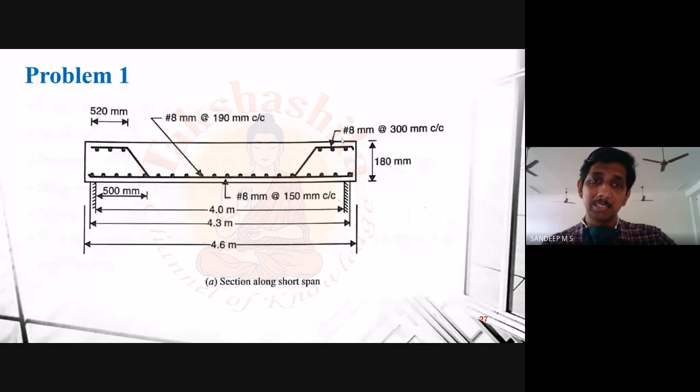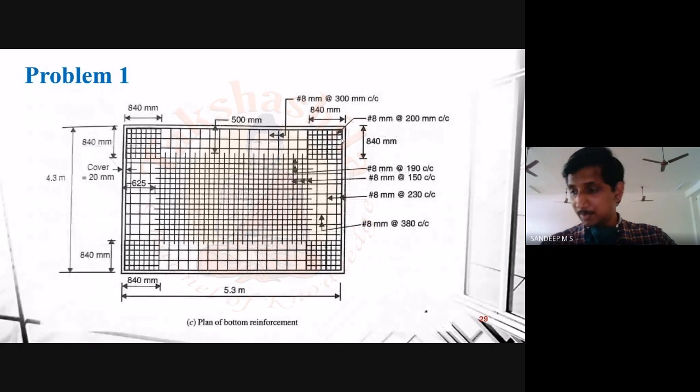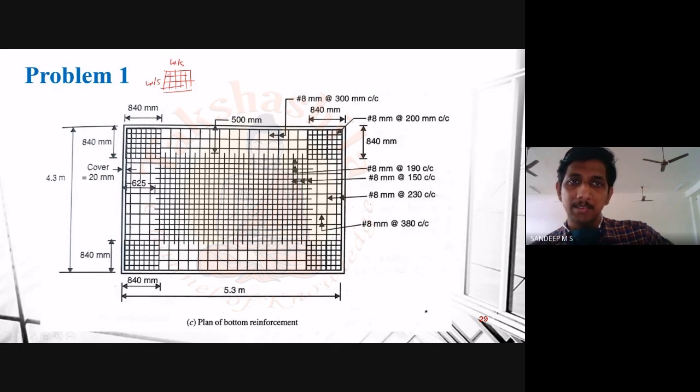So basically this mesh will be a square mesh, and it will be like this. This will be the mesh. Will be having many reinforcement. How to find the spacing of this reinforcement? That I will explain. So this is Lx by 5, and this side also Lx by 5. Okay, and now how to find the diameter and the spacing? So basically what you have to do is that you have to first of all take mx, my.